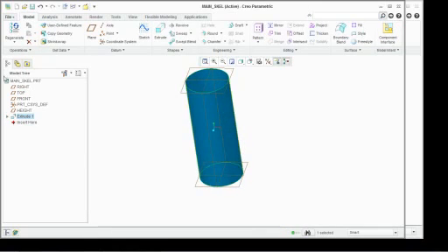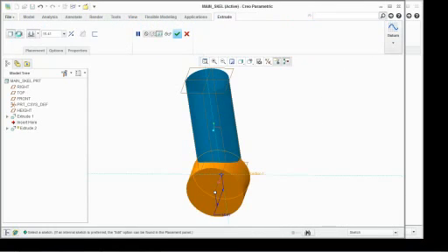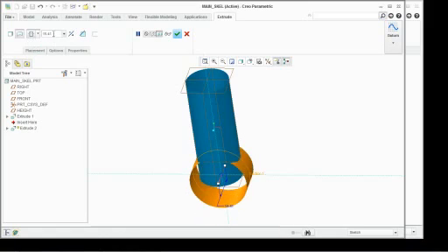Now we're going to select the front plane and create another extrusion, another circle based around the origin down there. This one's going to be a diameter of 28. Click OK. Make this one a surface as well. Make it a symmetric extrusion. And we're going to say this one is 32.